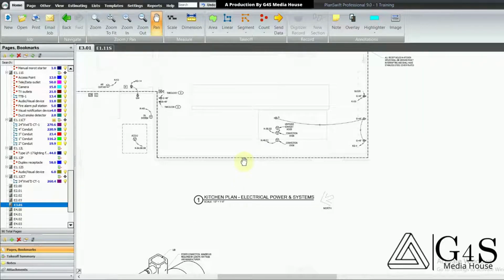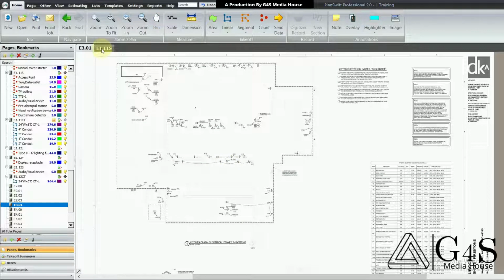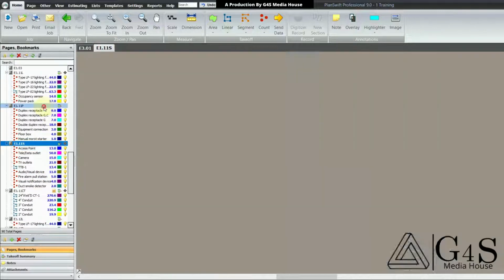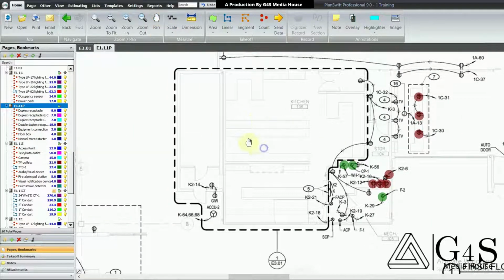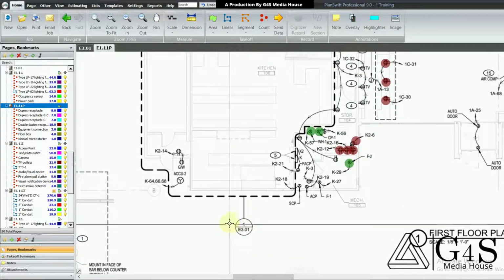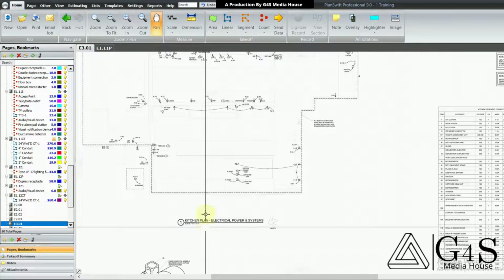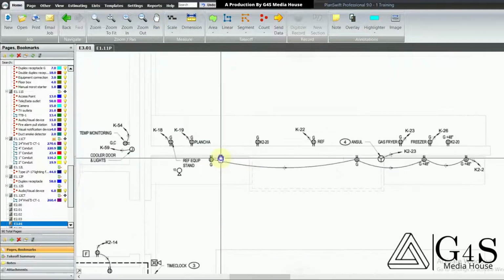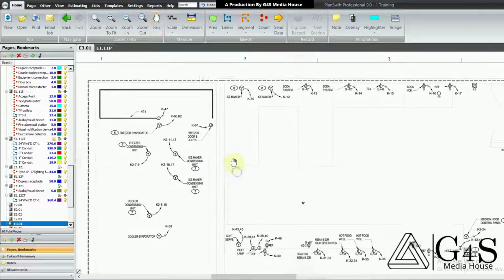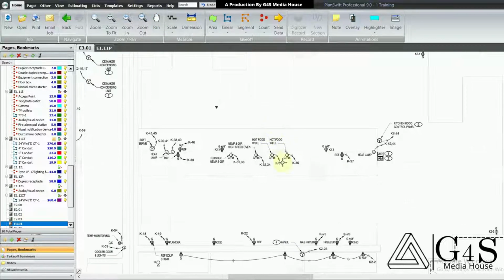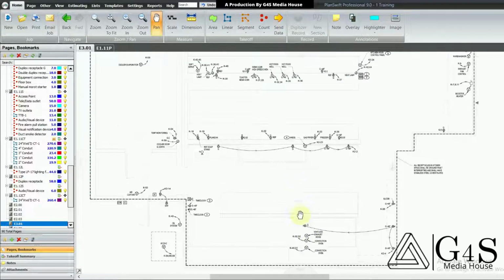So where was this plan cut from? Let's check the power drawing of first floor. So here is the kitchen plan on first floor. This plan was cut from here and is shown on drawing E301. So what we will do is count these devices on this enlarged plan. The method is similar to that of first floor and second floor power drawing count.